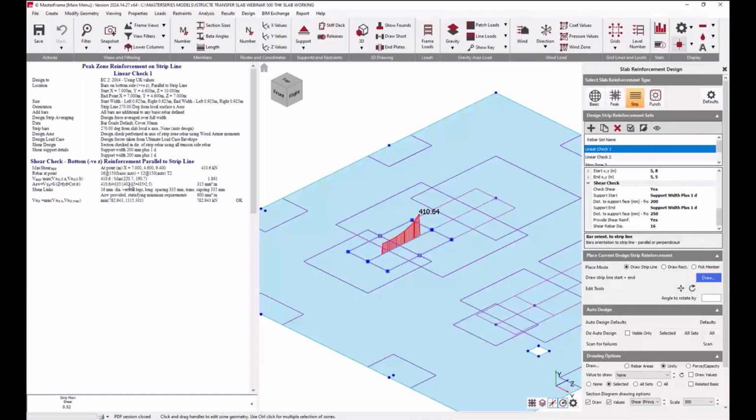So that's all being covered in that linear strip shear checking that's being done as part of that. And obviously, whatever the most critical point will be identified in this, and it will also tell you what side of the slab. That's telling you that the top reinforcement is actually being identified there as what is being used for the critical design section.